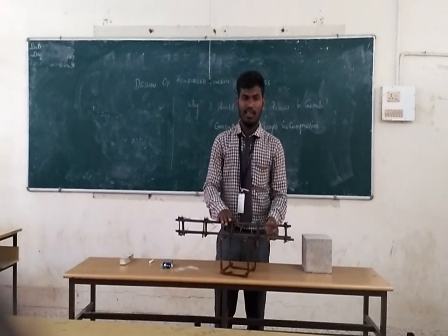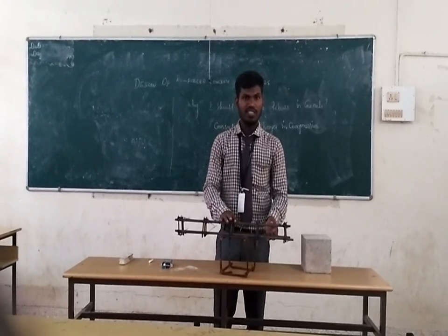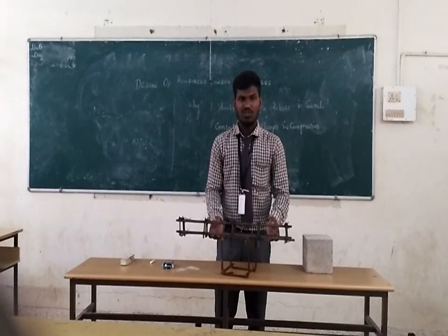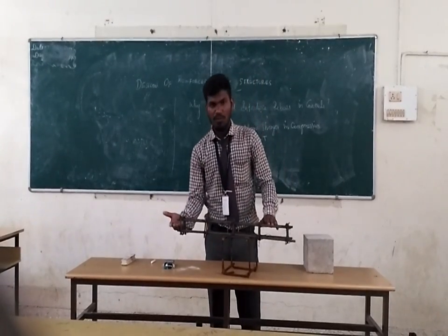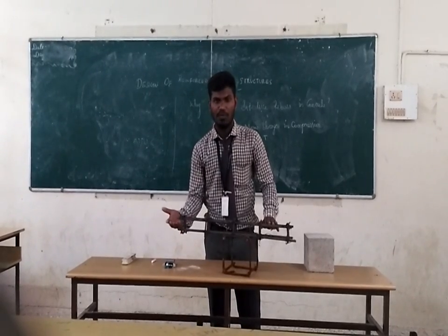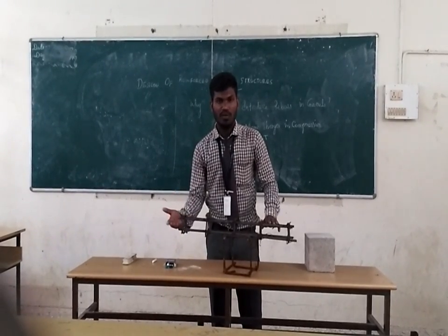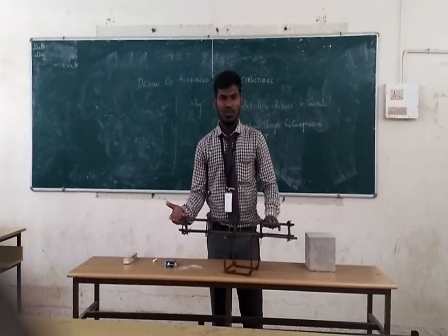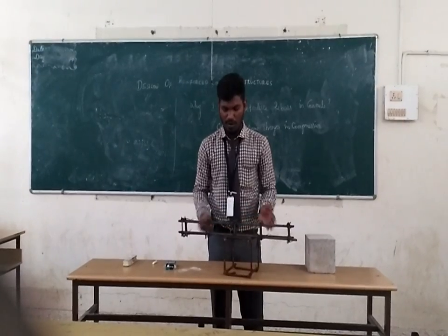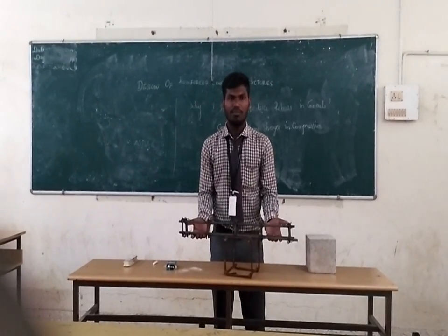As I said earlier, concrete is very strong in compression and very weak in tension. So the bottom of the section will be carried by the tension force and the top portion by the compression force. Since concrete is weaker in tension, the bottom will become brittle and break down.